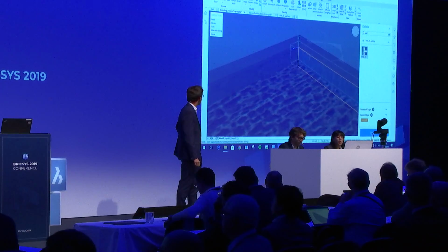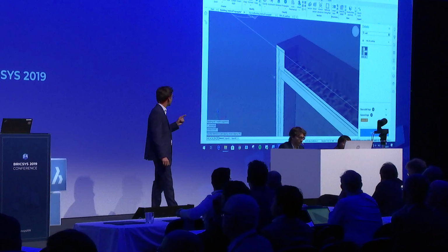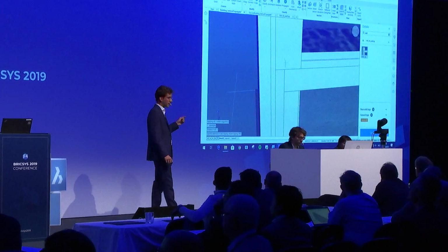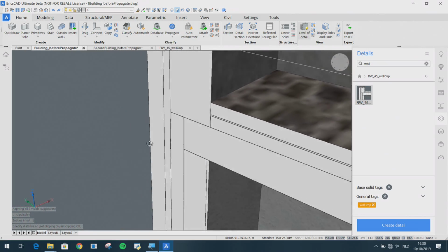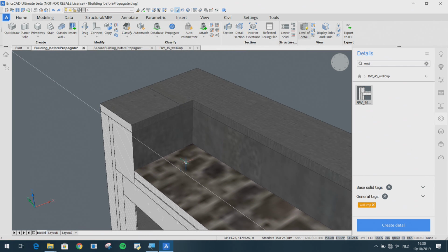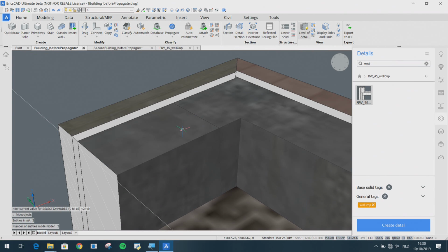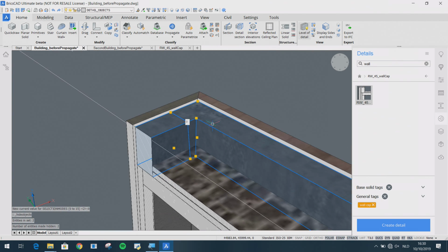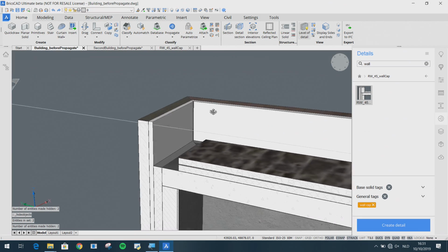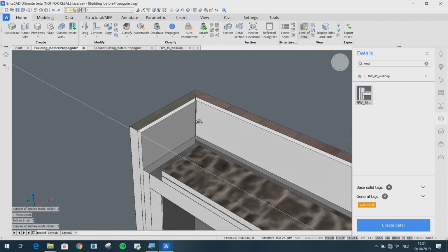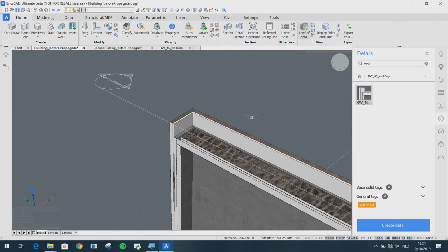And not only did it change the angle, it also changed the thicknesses of the plies at the backside, because there the detail is also nicely connected. So not only the angle, also the thicknesses. And here in this view, we can see that we actually had a 2D detail, but Propagate managed to nicely fix the corners between multiple details. So we see that we have a nice connection there, and if you're also having a closer look, all plies are meeting nicely together.